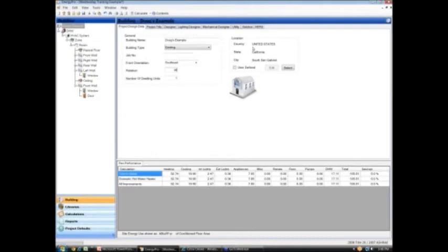If you're not a power user, leave rotation alone and put in the walls at the actual orientation of the walls, the roof, the actual orientation, and all that. Don't try to do it here until you become a power user. And when you're a power user, you don't need to listen to me do this. I'll be boring to you.